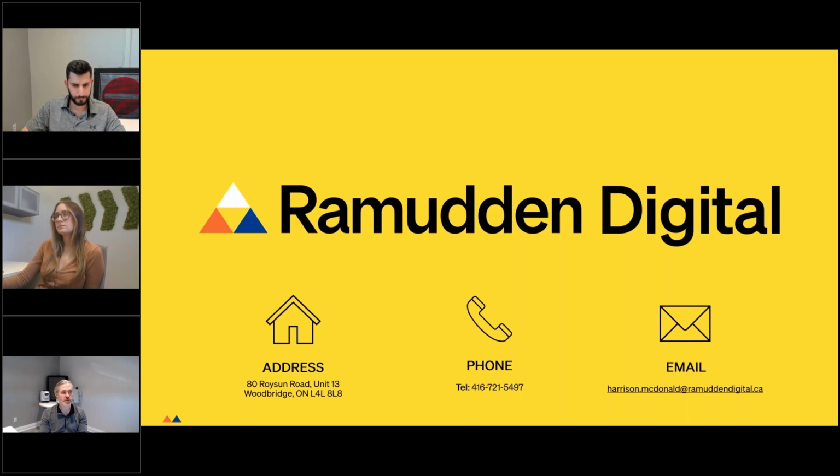So where I would see that being used is during a time of day restriction. So if you had, say, during the AM peak and the PM peak, you're going to turn on that right turn or left turn restriction for 3 or 4 hours a day, then that's the correct use of the dynamic sign. But if you wanted it to be only on red, you can't just have it come up on the red signal for that specific approach and have it be enforceable, because it's not clear to the driver that the signal is relevant to that movement. So that was one finding that came back from York's review: if you want it specific to that signal phase and not general across all phasing, then you need to use the larger sign, which includes the legend, to make it clear that the red signal is relevant to the movement restriction.